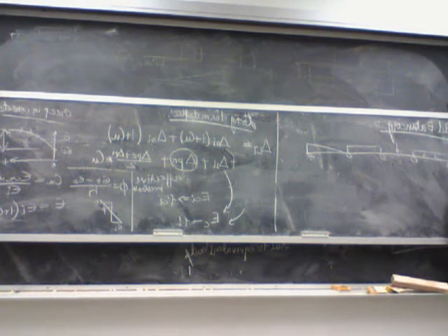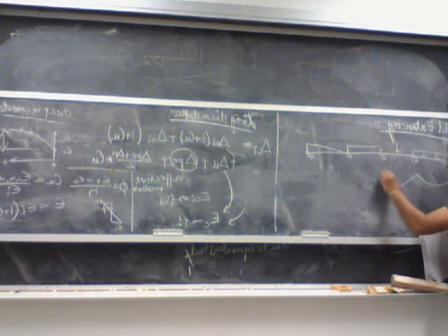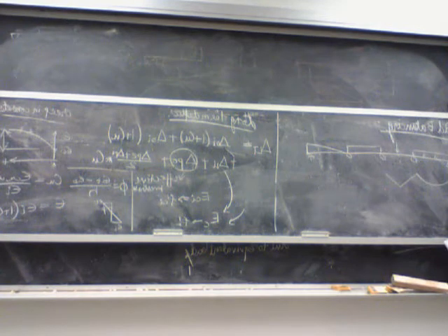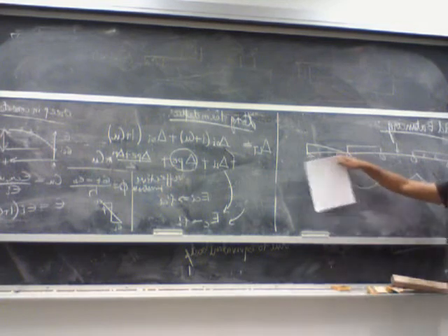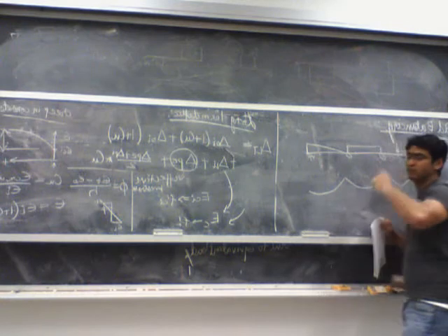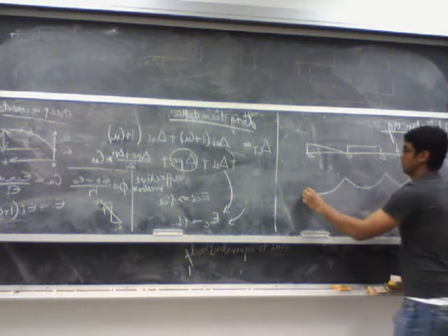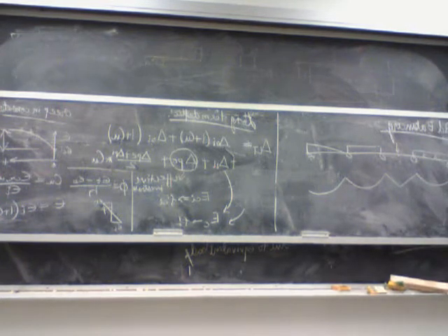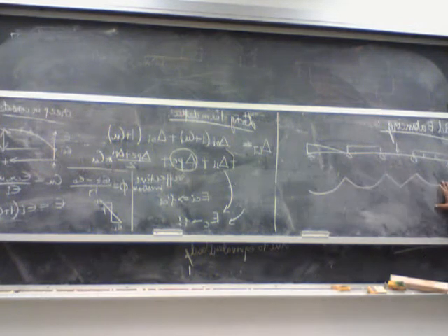So I know that in order to balance a distributed load, I need to provide a parabolic tendon in this span. In this span, since it's a point load, I need to provide something which has this kind of tendon profile. Again, for this one, I need to provide a parabolic tendon. And for this case, I don't have a parabolic tendon. Most probably it will be a tendon which follows a cubic equation instead of a quadratic equation. So what you want to do is find out what is the prestressing force and what is the actual tendon profile that you need.